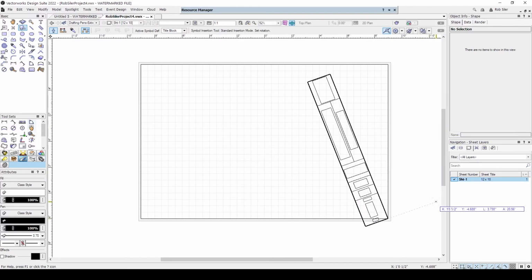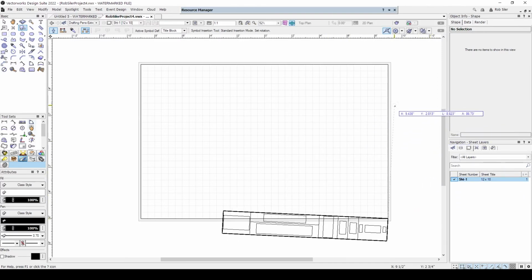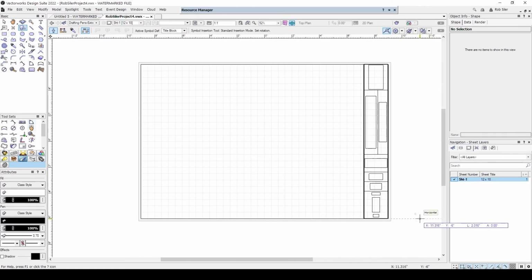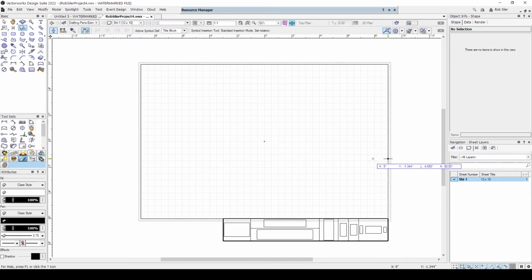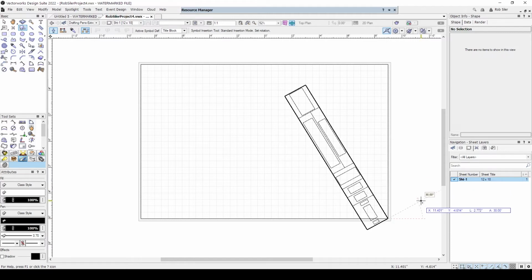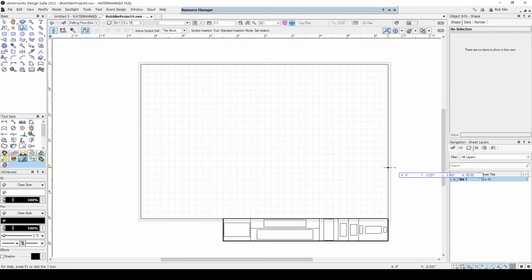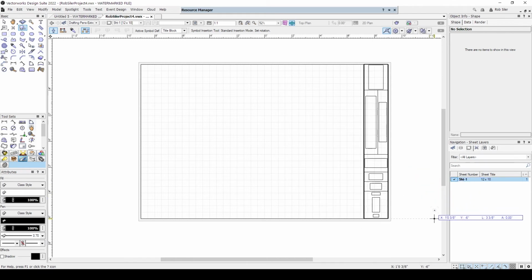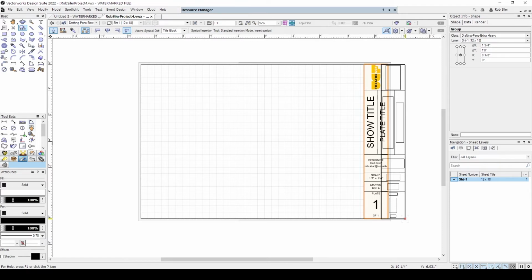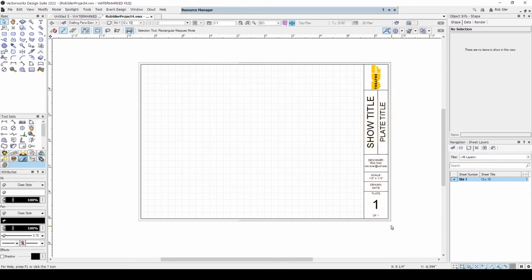The second click is going to set the rotation. If you don't move your mouse, odds are it's going to stay completely vertical. If in doubt though, hit the shift key and work your way back around. That shift key on rotation is what snaps you to different angles. So I'm going to press and hold shift till it's vertical and lock it into place.